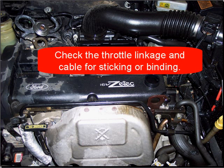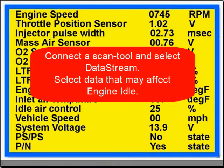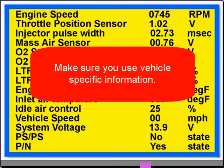When analyzing any idle problem, check the obvious things first. Things like throttle linkage and cable for sticking or binding, and then connect a scan tool and select data stream. You want to select the data that can affect engine idle. Make sure that you use vehicle-specific information and specifications. You cannot find problems with bad specs.